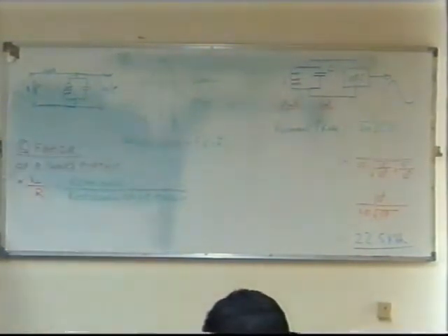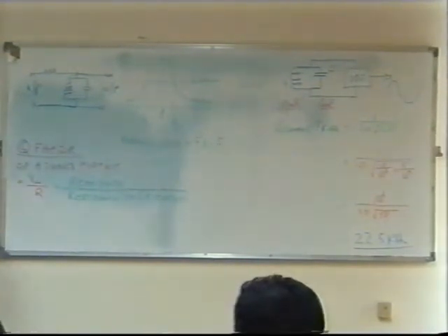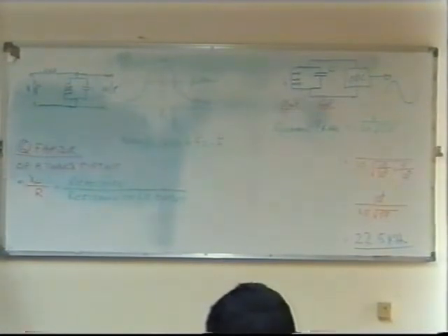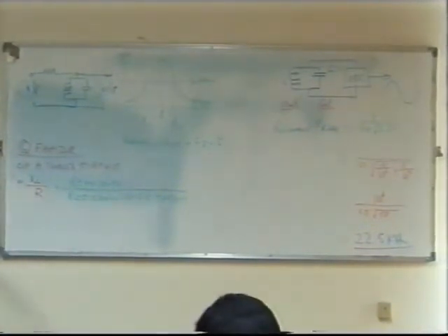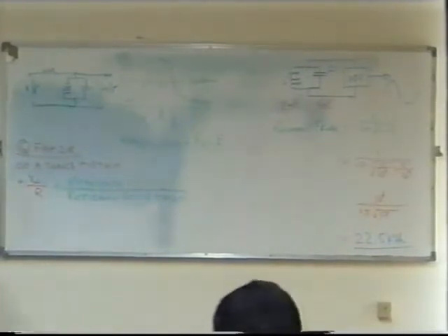Any power loss in there, this heat, appears as resistance in the circuit. The ratio of XL over R is called the Q factor of the circuit: reactance divided by resistance of the LC circuit. This is not the same resistance as this. This is something different. This is just of the tuned circuit.